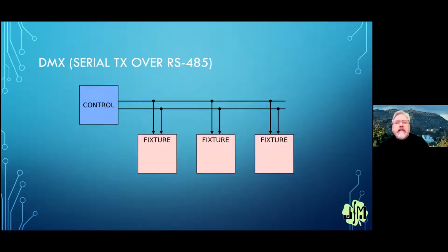The thought behind that is if we get some kind of electrical interference that impacts one wire, it will impact the other wire equally because they're laid on top of each other and twisted. That way, if a voltage wanted to push the levels up, they would both go up so that the difference between the two outputs would remain steady.